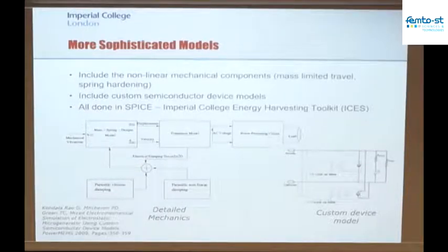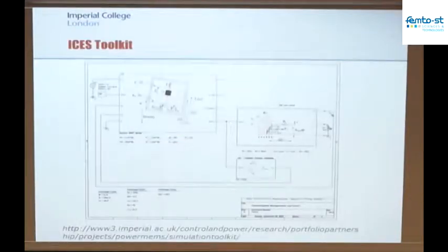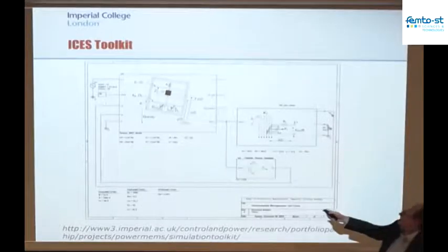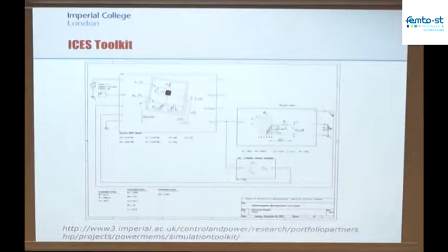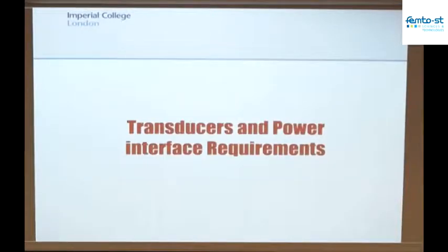So that generally means that the linear systems are going to be quicker to simulate, and that once you start adding in these nonlinearities, simulation time can balloon. But it's all in there in this toolkit. You've got linear, non-linear dampers, different implementations. You've got piezoelectric transduction, electromagnetic, and electrostatic. Feel free to have a play around with that.